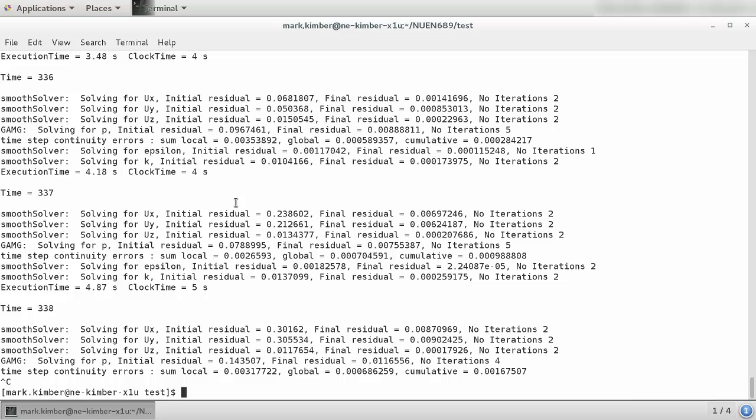If you're going to use Octave like I did here, then you're going to want to use the function griddata, which can take two vectors and a velocity or some profile of something else like kinetic energy, for example. And then you tell it which points you want to interpolate to. You can specify whether it's a linear interpolation, a cubic interpolation, nearest neighbor, I think, or some other options as well.